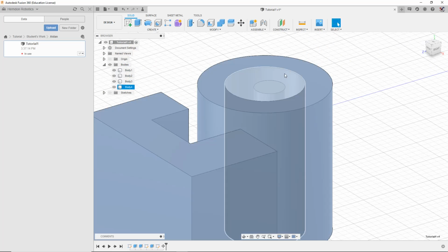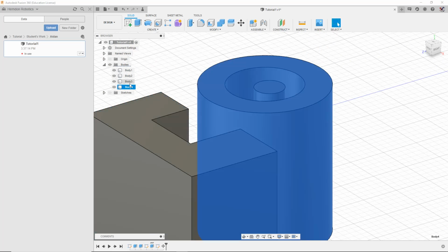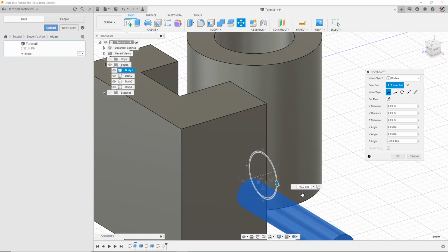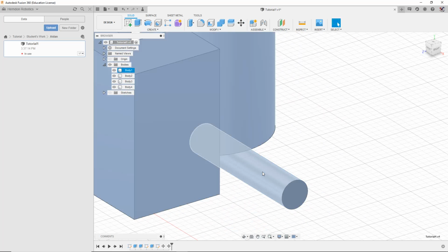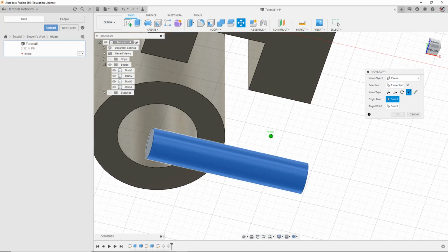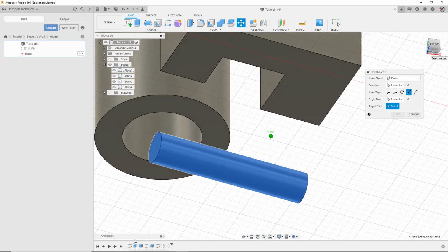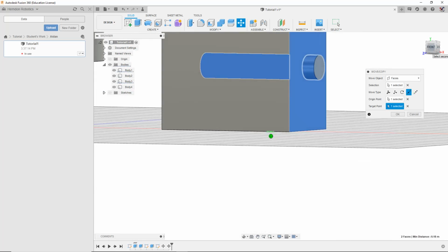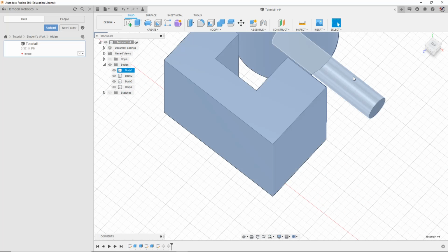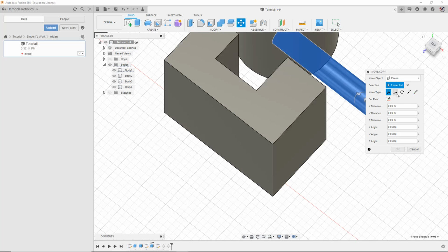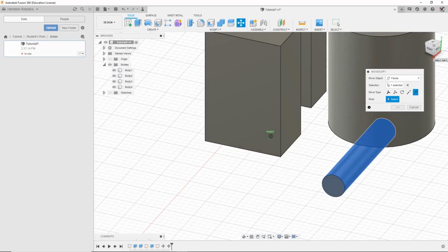What I normally do is I do a bit of work on it first. So I come here to this iris, I hit move, I angle it down to 90 degrees, I hit OK, I hit move again, I go point to point, select this point, come up, then I select this point, and it gets moved there. I don't know why it moved there, but I hope you're getting the idea. You can use that to basically attach pieces without attaching them, which makes no sense right now, but it'll make sense in a minute when I show you joints. So then I can come here.